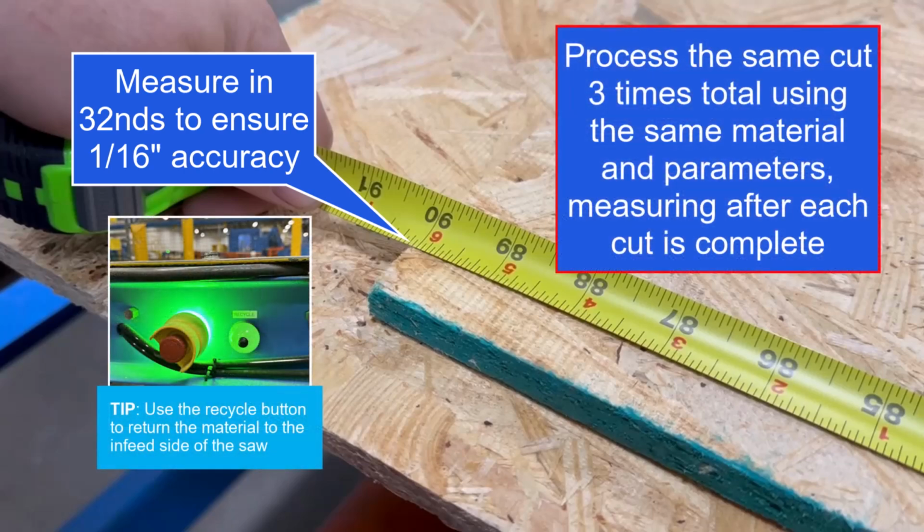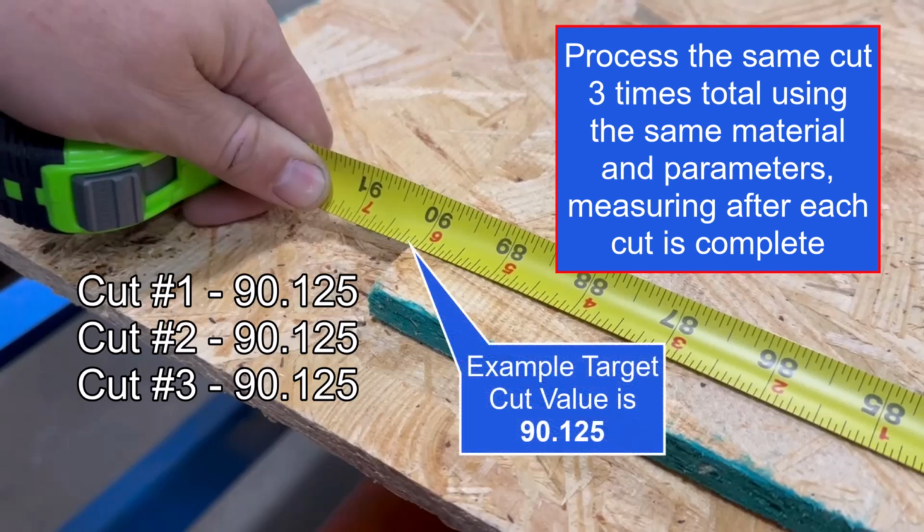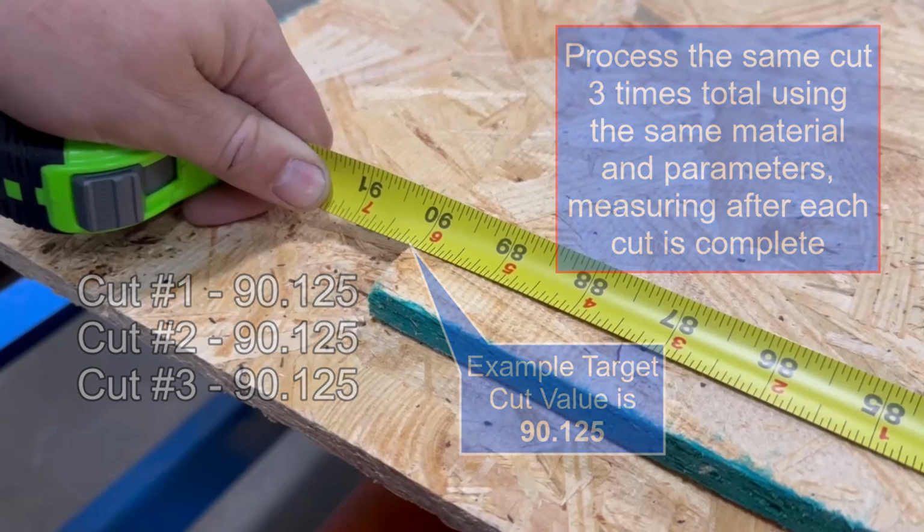Turn the material to the in-feed and process it 2 more times using the same cut parameters with the semi-auto function. Again, measure the crosscut, then record the results. Compare the 3 results to see if they are identical. If the results are identical, use this figure as the target cut value. For this example, the value is 90.125.